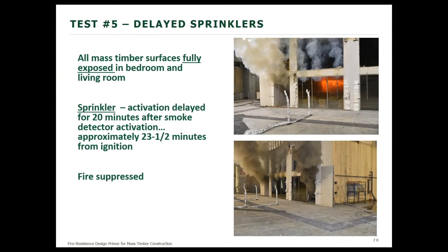This slide shows you test number 5, which had the delayed sprinklers. Again, fully exposed, all mass timber surfaces fully exposed. Sprinkler activation was delayed for 20 minutes after the smoke detector activation, which essentially is about the same as the fusing of a sprinkler. So at approximately 23.5 minutes from ignition, the sprinklers were charged, and